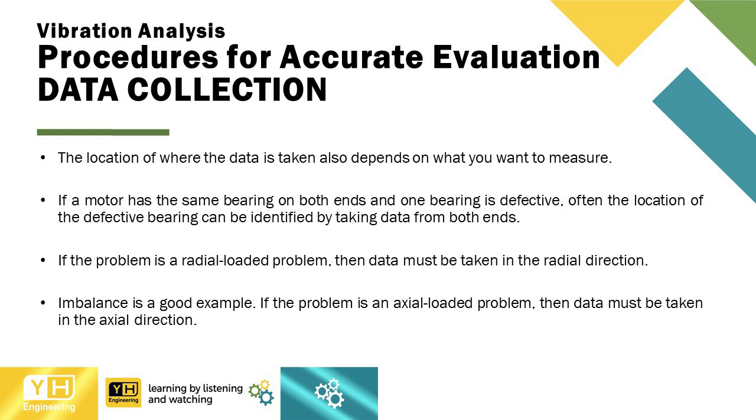The location of where the data is taken also depends on what you want to measure. If a motor has the same bearing on both ends and one bearing is defective, often the location of the defective bearing can be identified by taking data from both ends.